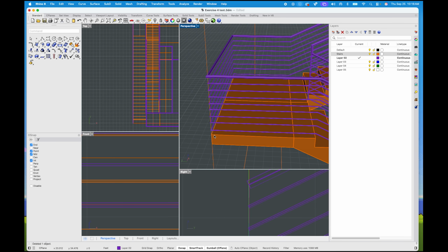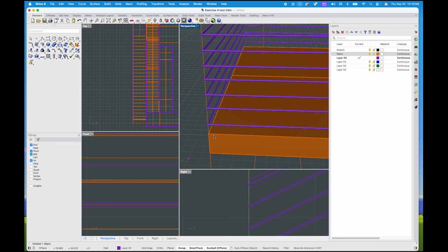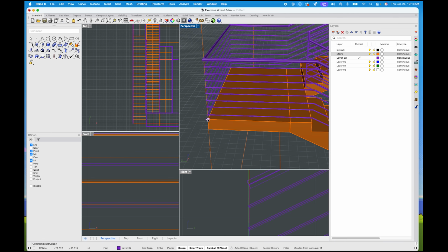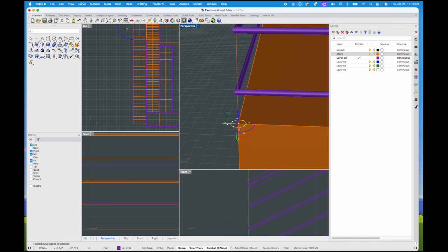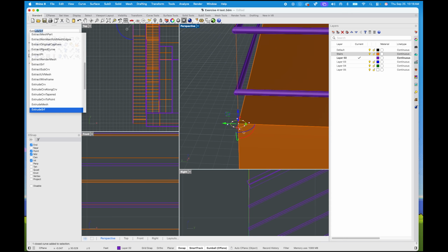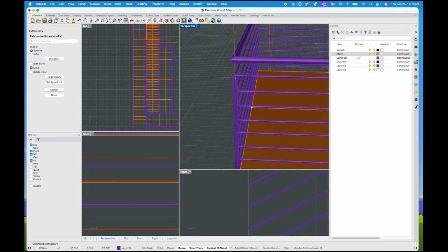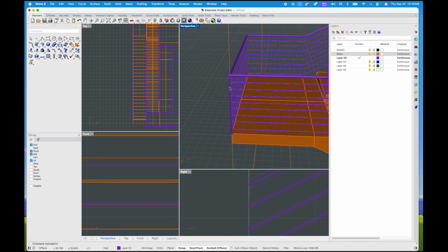But yeah, we just need a piece. So in my case, let's just do it with a circle because it is a little bit easier, at least for the amount of time that I have. So I'm going to start off with a small circle and basically extrude it. Oh, not extrude face, but make sure you extrude curve. There are a lot of different extrudes. Keep in mind, only certain ones work with other ones. So that's looking pretty sweet.